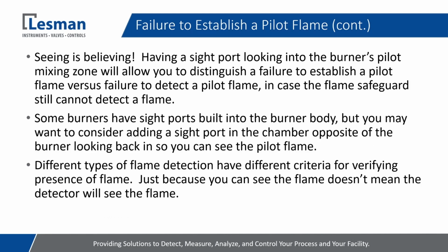Seeing is believing, right? I come across this all the time, where I'm doing a commissioning on a system and I'm looking through either the sight port in the chamber or back to the burner, where I can see the flame. You can see that nice blue glow, but for whatever reason, the flame safeguard is still not seeing it, right?